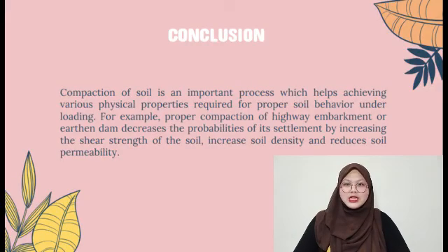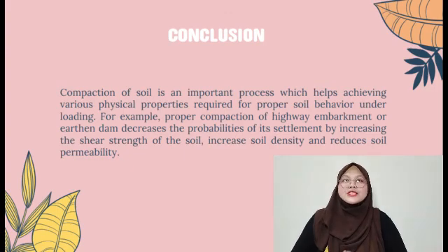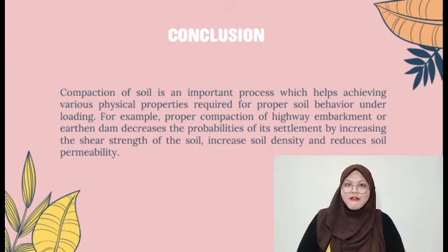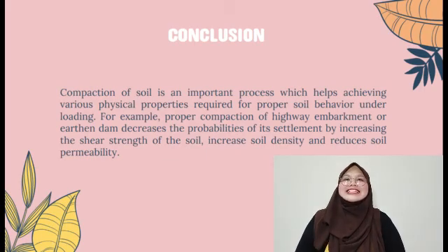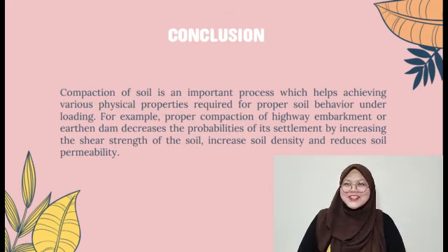In conclusion, compaction of soil is an important process to help achieve various physical properties for proper soil behavior under loading. For example, proper compaction of a highway embankment can decrease the probability of its settlement by increasing the shear strength of the soil, increasing the soil density, and reducing soil permeability.